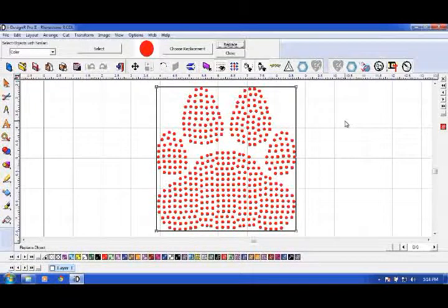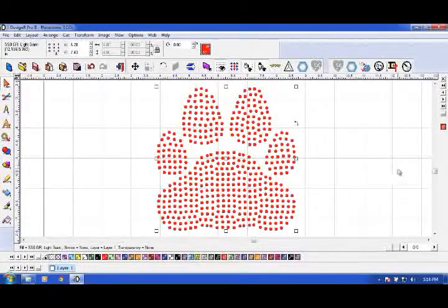The benefit to this is the ability to change the rhinestones quickly if we need to later on. In other words, this operation puts the imported pattern in a format that it recognizes. We can now click Close. By the way, this Replace with Rhinestone function is also a good way of converting patterns that you have designed in DesignR PRO 2 as well. You might find a case where you have a current pattern where you need to change the size of the rhinestones, and this is an easy and simple way of doing this.